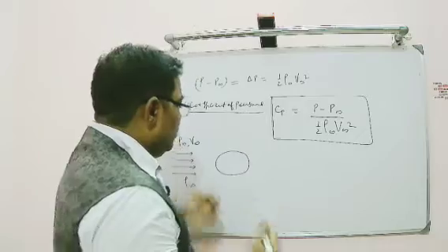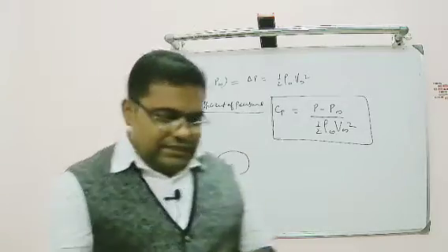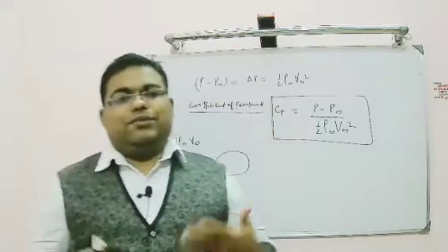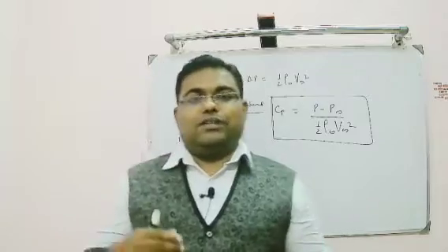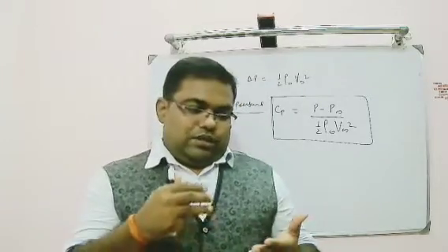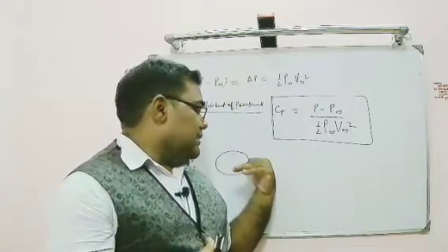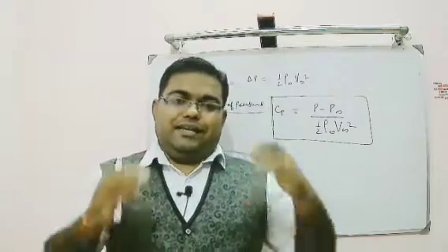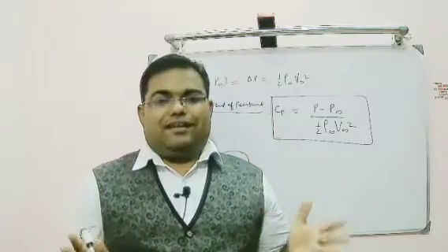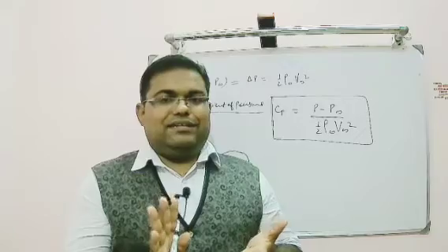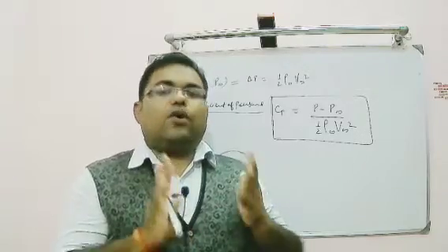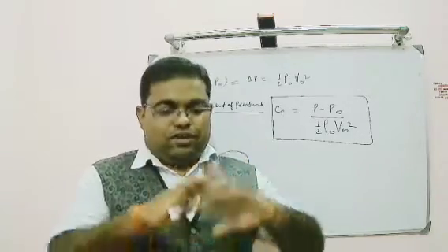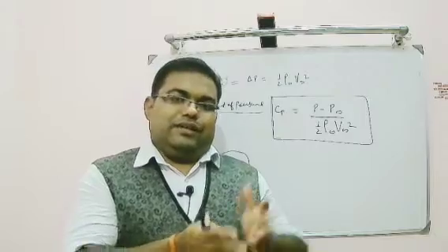So how to do so? If we look at the traditional way of experimentation where we find out Cp, how do we do that? Usually we mount this object inside the test section of a wind tunnel. We need a wind tunnel. A wind tunnel is a device which maintains a constant atmospheric pressure, or controlled atmospheric pressure, in a given domain.